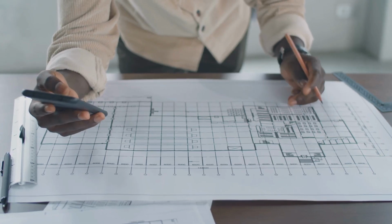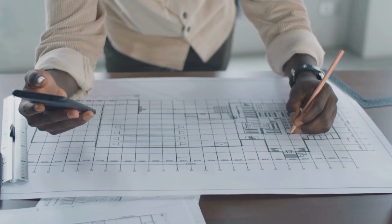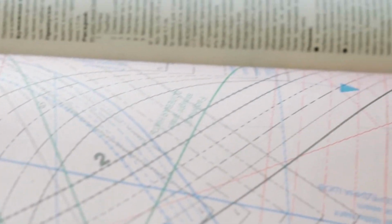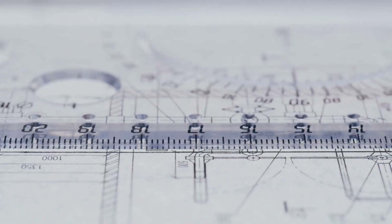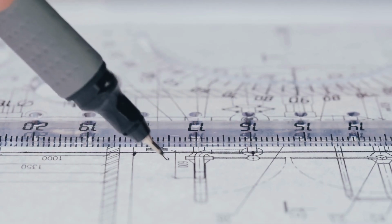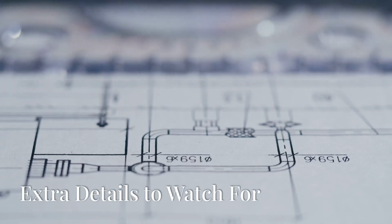To visually represent the slope, blueprints often use a triangle symbol. This symbol helps to quickly identify the slope on the plans. The steeper the triangle, the steeper the slope. This visual cue is an easy way to understand the gradient at a glance. You'll also usually see an arrow indicating the direction of the slope, showing you where the water will flow off the sidewalk. This ensures that water is directed away from areas where it could cause damage or hazards.